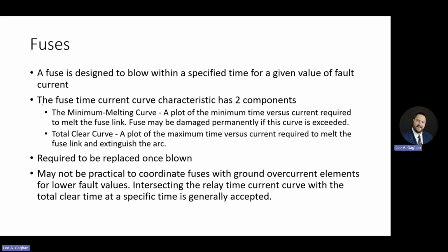Once that squirrel catches on fire and falls to the ground, we're good to reclose. Sorry if you like squirrels, but with a fuse that doesn't matter, right? We're still sending someone out there to replace the fuse, and you're going to be out of power for a couple hours. So, biggest disadvantage.